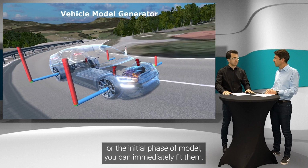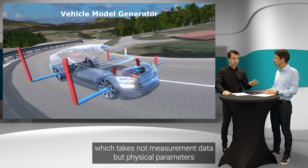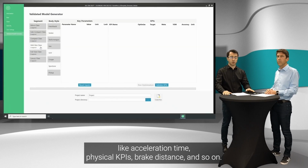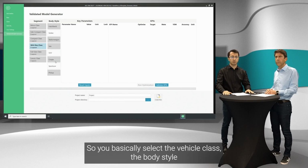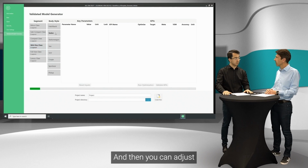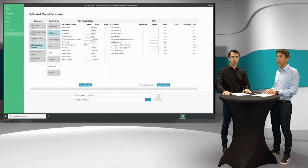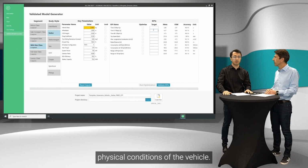What we implemented to cover this gap, also during the initial phase of model buildup, is that you can immediately fit them. We created this vehicle model generator, which takes not measurement data, but physical parameters like acceleration time, physical KPIs, brake distance, and so on. And then the model will be fitted. So you basically select the vehicle class, the body style, a base vehicle would be used, and then you can adjust the inputs that you have for this vehicle.